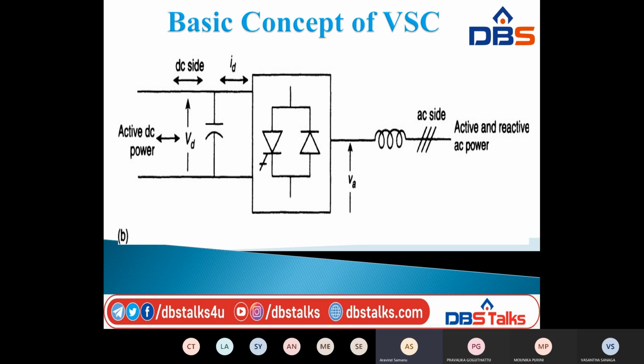Because the capacitor is large enough to handle a sustained charge or discharge current that accompanies the switching sequence of the converter valves and shifts in phase angle of the switching valves without significant change in the DC voltage, the DC capacitor voltage will be assumed constant.